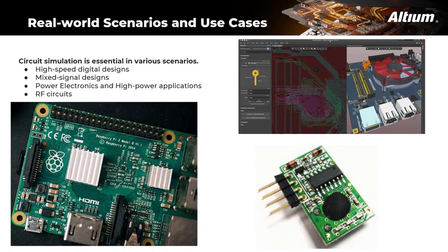Next, mixed signal designs, which combine analog and digital components and often present unique challenges. Simulation plays a vital role in understanding the complex interactions between these components and verifying that the entire system functions as intended. For example, designers can perform sensitivity analysis to determine the impact of component tolerances on an ADC's performance, helping to optimize the design and ensure accurate signal conversion.